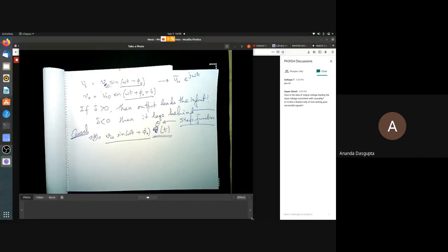Okay? So the way you would actually handle that is using Laplace transform properly, because Laplace transform takes into account the fact that the signal starts somewhere and the integral is only from 0 to infinity, not from minus infinity to plus infinity. Or you could simply say that fine, there would be something happening at the beginning, you would just ignore that and we are only looking at the steady state a long time afterwards.